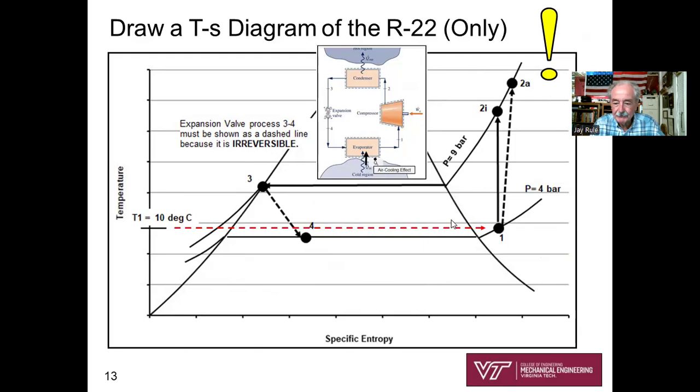This is going to help you keep straight. So this is why I've drawn state 1 as slightly superheated vapor, okay? The compressor is increasing the pressure. That helps you visualize that coming out of the compressor, you have a superheated vapor. So you don't have to memorize it. You have to look at the TS diagram to see, oh, I see, I've got a superheated vapor coming out